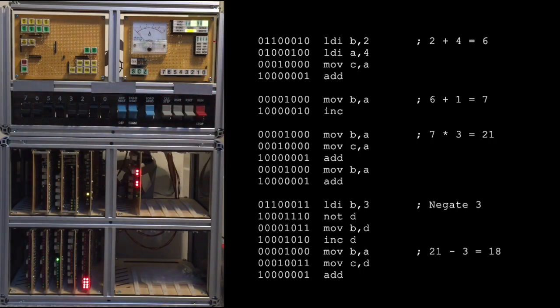There's more to this than meets the eye, and what I've done is wired the switch to both the control lines but put a capacitor over the select DS line so that it's held on slightly longer than the load instruction line. This ensures that the value latches before it's removed from the bus. You can't really see what's happening with the naked eye, but without it you will get erratic behaviour where sometimes the register just won't load.